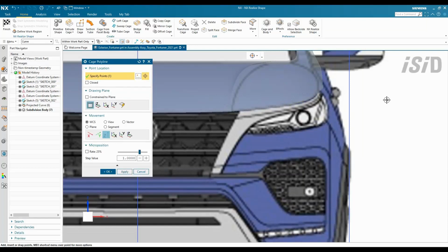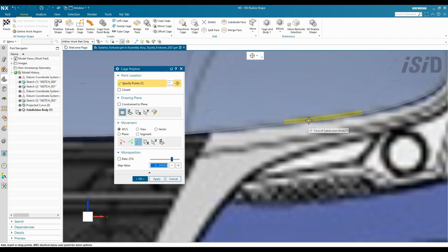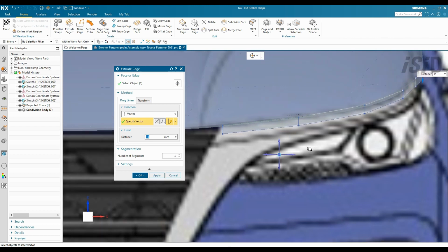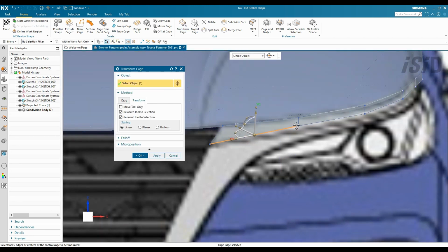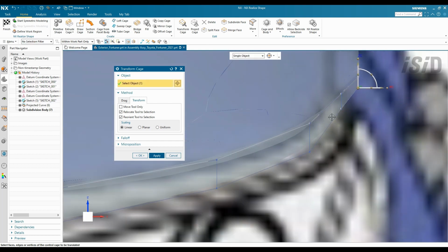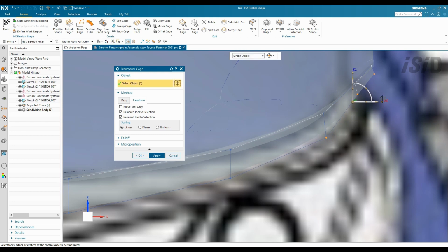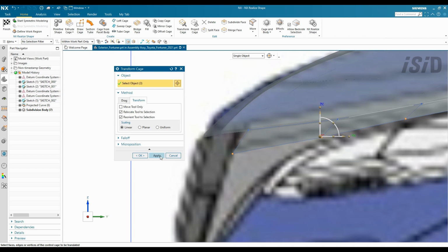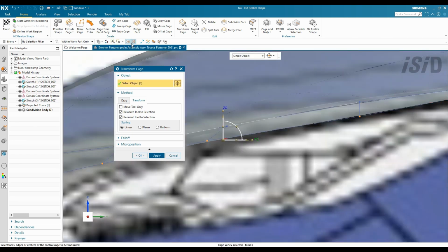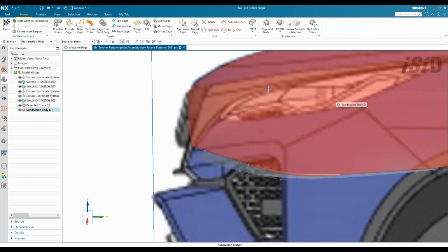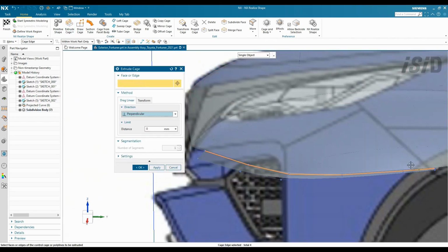And then I'm going to create some accessories near the headlamp using cage polyline, and then extrude the cage polyline so it's going to be the surface, and continue again refining using transform cage. Okay, using the same step, I continue to refine again this shape.